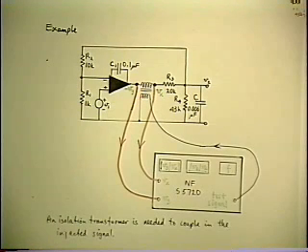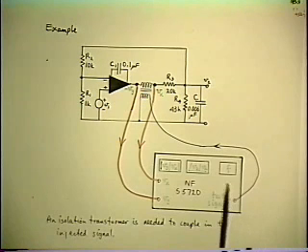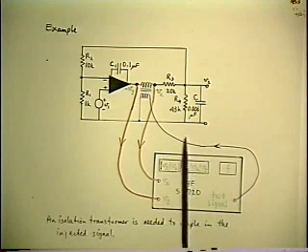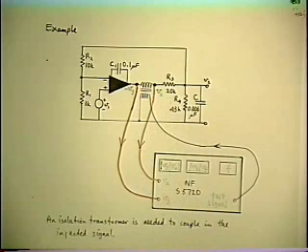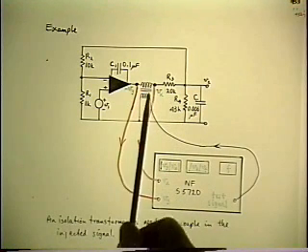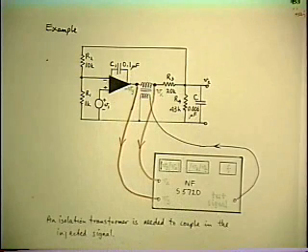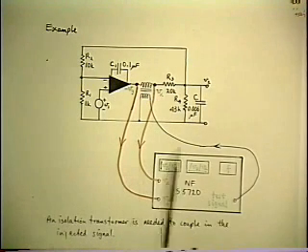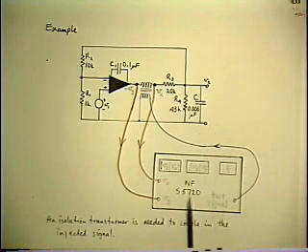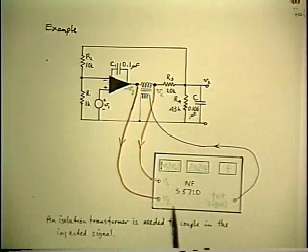And even if you did find one, it doesn't tell you anything about its properties. It may have an obscure part number on it, and that's about all. So you don't know the turns ratio, the magnetizing inductance, the frequency response or anything. And in any case, it's probably 10 times bigger than the rest of the circuit physically anyway, and it does nothing but pick up hum. So this is not a very attractive solution.